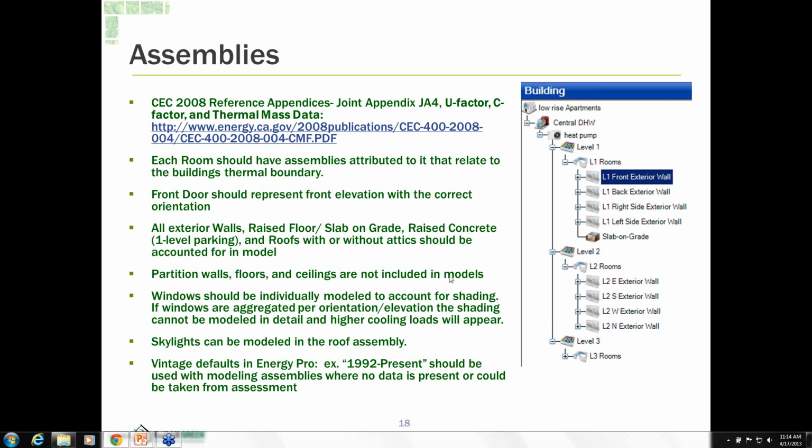So there are 2 different tabs: residential mechanical ventilation and actual exhaust fans. But you can email me at the end, and we can maybe go into how we can work on non-res and exhaust fans. And yes, you want the total CFM, so add up all the CFMs, and I think for horsepower you want to average it, but you want the total CFM.